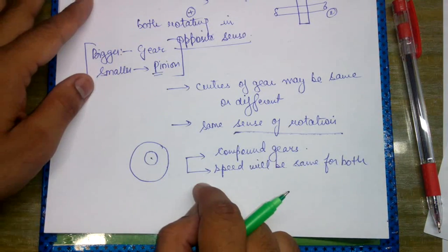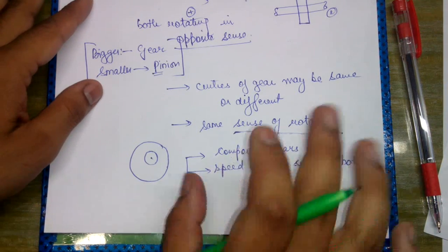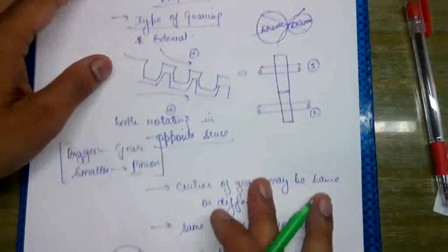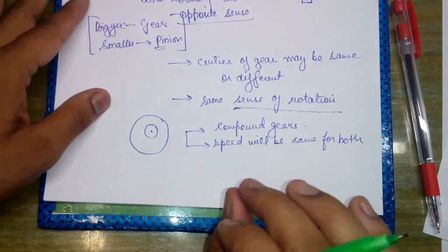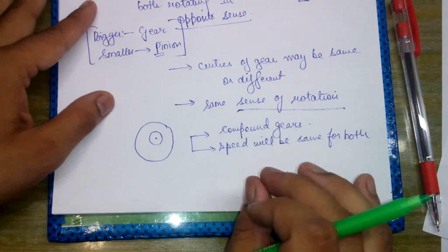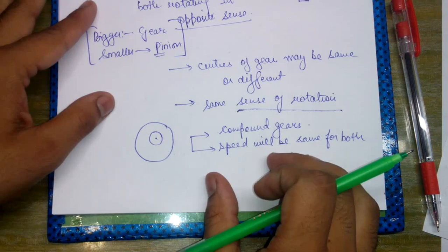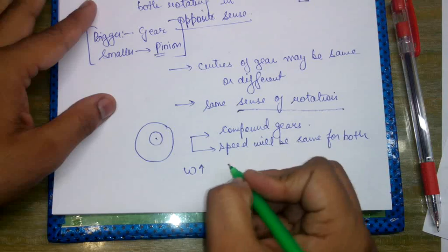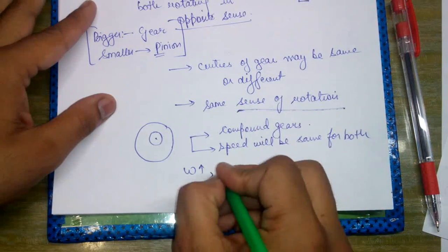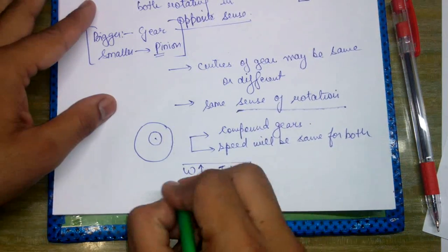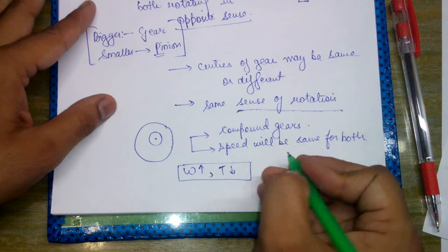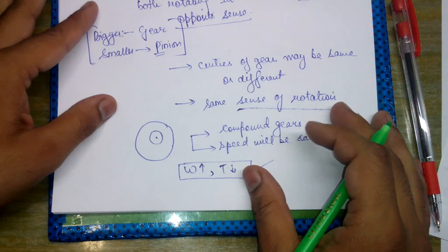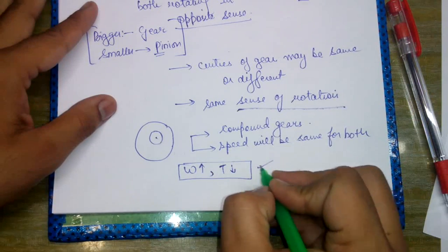And generally the smaller bodies are made pinion or the drivers. I have already told you, I made a correction. I actually accidentally told you something wrong, but the correction is the smaller bodies are generally made as the drivers for power transmission. Why? Because they can rotate at larger omega. Omega for the smaller bodies would be large, and since they are small, the number of teeth on their external surfaces would be less. Okay, and hence they are generally used or made as drivers for the power transmission, and omega is large and the teeth are less.